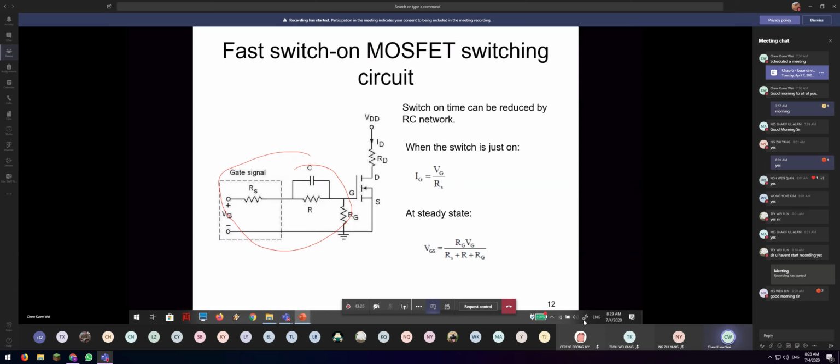Okay, so when you first turn on the timer, the voltage will slowly build up at the capacitor. In other words, the capacitor starts as a short circuit. Because before I turn on the power, the capacitor basically has no voltage, so it's a short. But when I switch on the switch, the voltage will slowly charge up the capacitor. So it will charge up in this way, the VC, slowly like this until it achieves saturation. So that's why it always starts with a short circuit here.